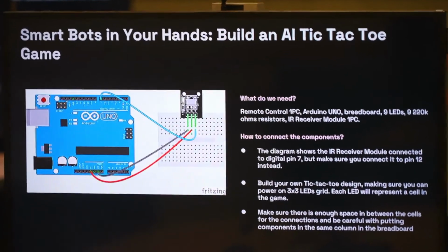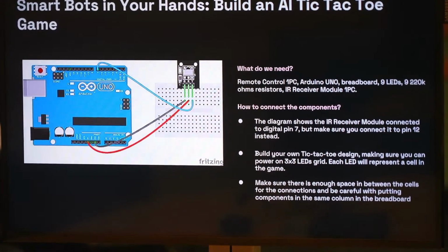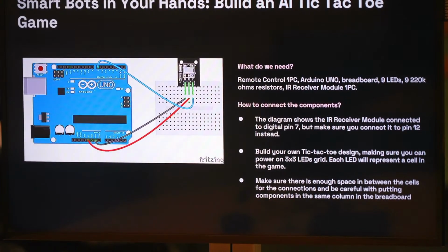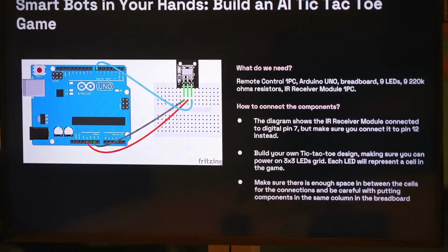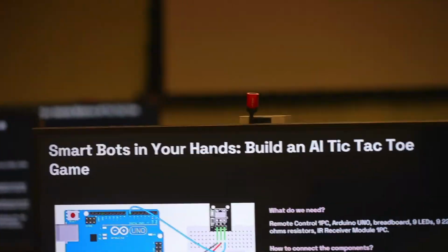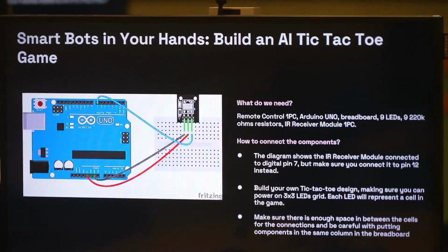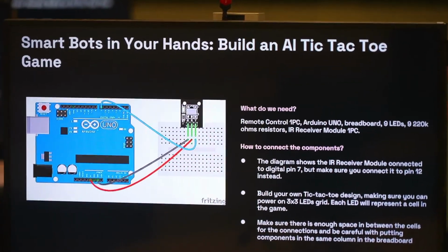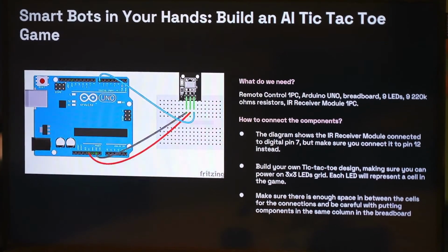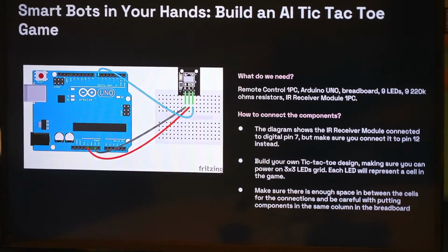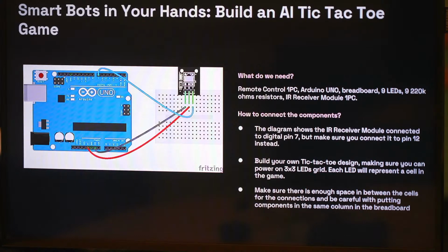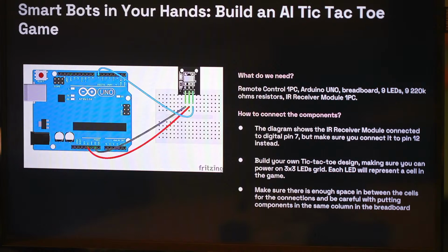And what you can do is connect one ground here from the Arduino. Instead of using more cables, you can use the resistor on the other pole. So the negative one, this was the longer one? Yeah, this is the long one. Okay, so you can flip it. Now the resistor is connected to the negative side, and then you just do it like this. So you save one wire for each LED. And then you just connect the digital pin to that one.